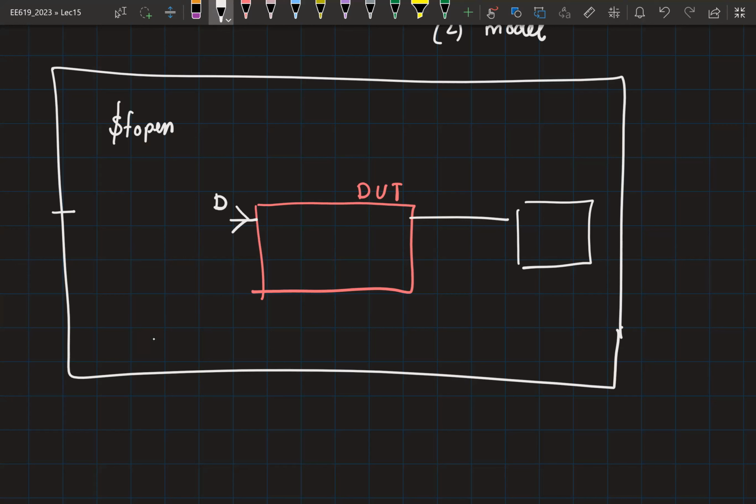Now, another very nice usage of this non-synthesizable code is finding the activity factor of a particular net based on simulations. What actually happens is you feed in the input pattern that you want, either from another module in the test bench or you pick it up from a data file. And then you dump the information about how this node is switching into another file.